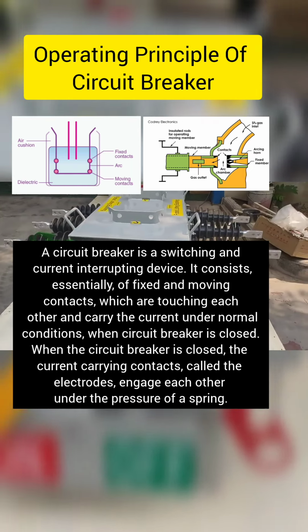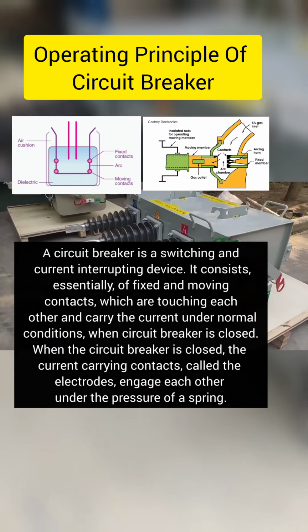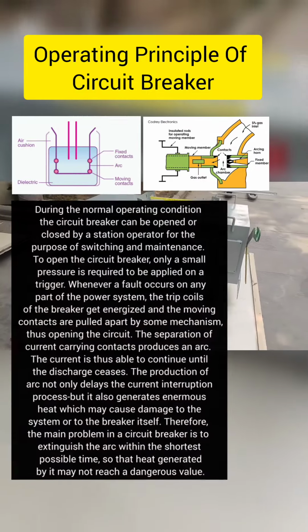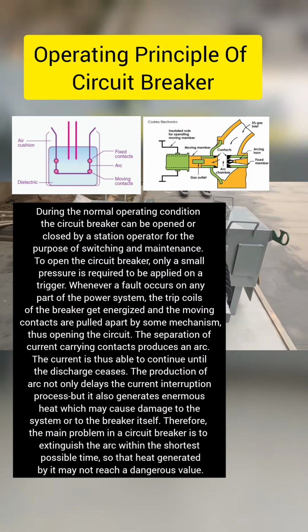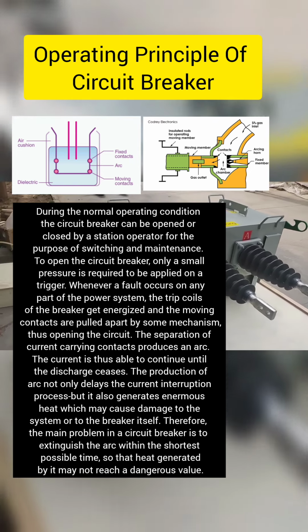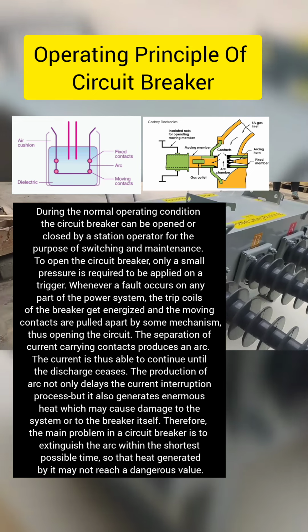When the circuit breaker is closed, the current carrying contacts, called the electrodes, engage each other under the pressure of a spring. During the normal operating condition, the circuit breaker can be opened or closed by a station operator for the purpose of switching and maintenance. To open the circuit breaker, only a small pressure is required to be applied on a trigger.